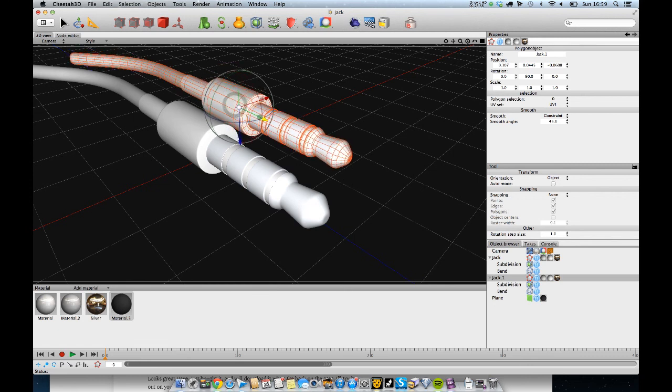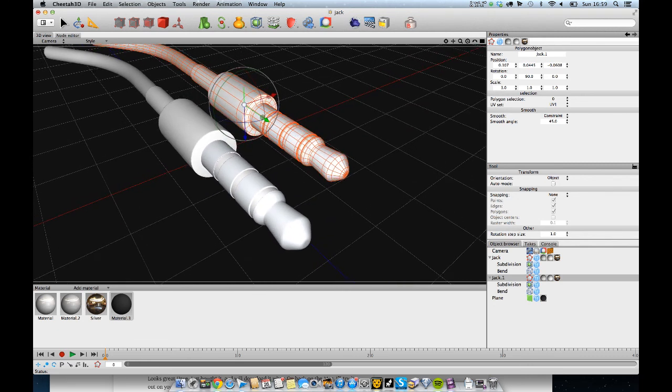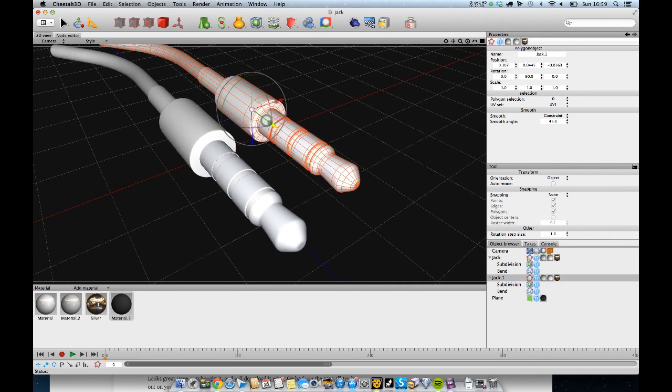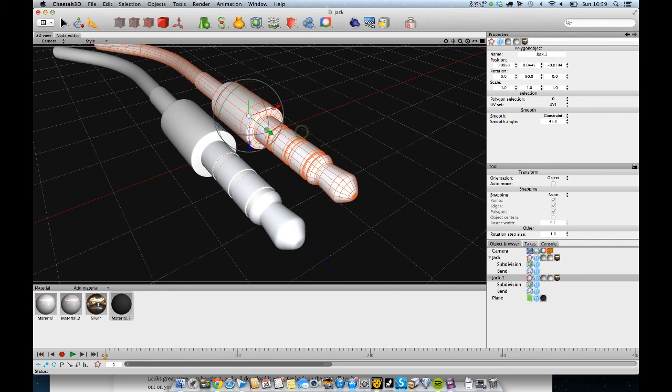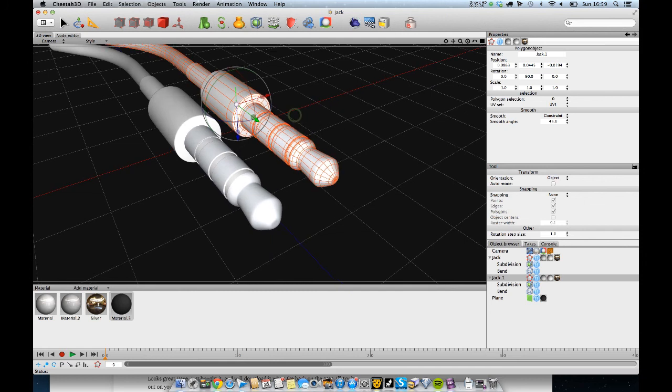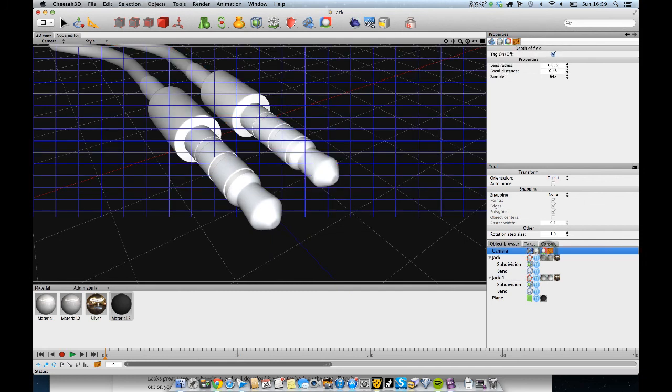I remember doing this on the first render. Basically because I want the focal point to be the same on both. I think it will make for a more interesting render. So let's just have a look at that depth of field again. So that is falling kind of across the two jacks, somewhere like that. I quite like that. I'm going to just crank this up a little bit to somewhere around 0.1.